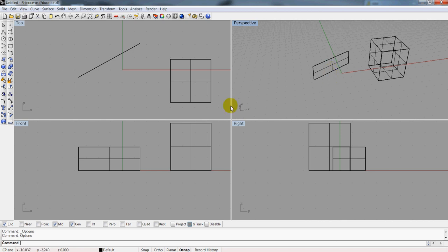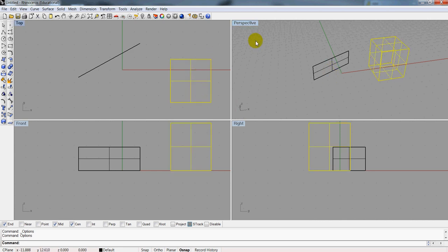So one of the nice things about Nudge is that you can select something, and then using just my arrow keys, I can nudge it a given amount of space. If I hold down Shift, I nudge it more. If I hold down Control and hit the arrow keys, I move it less. So Control decreases your movement each time, Shift increases.